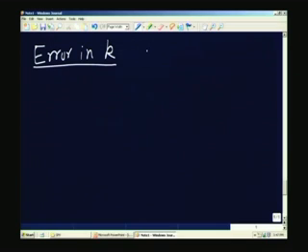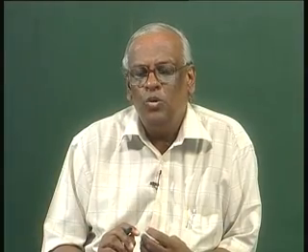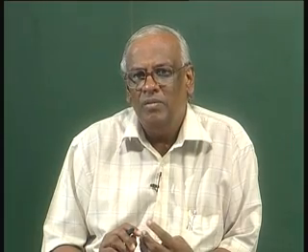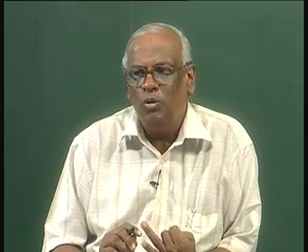I have to use the error propagation formula, which is familiar to us. We dealt with it in our first module when we were talking about estimation of errors in measured quantities. In this case, we are measuring Q, the heat transfer per unit area per unit time. We are measuring thickness, and we are also measuring the delta T. All of them are prone to errors.